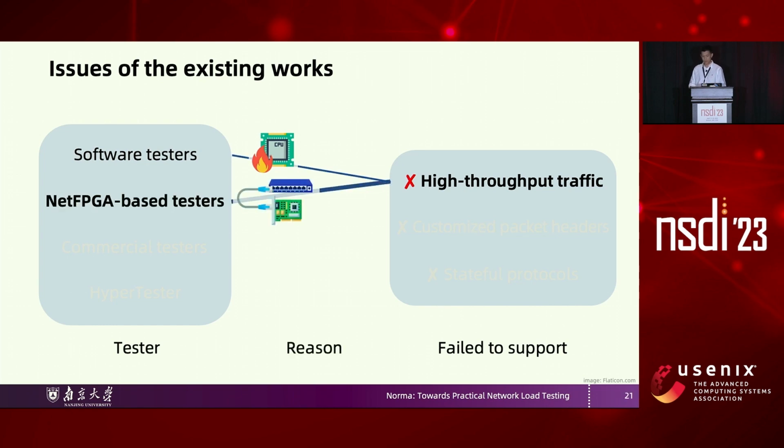NetFPGA-based testers use FPGA to generate traffic. On the common NetFPGA platform, there are only one to two network ports, so using it to test 32-port switches and other network devices is too expensive.